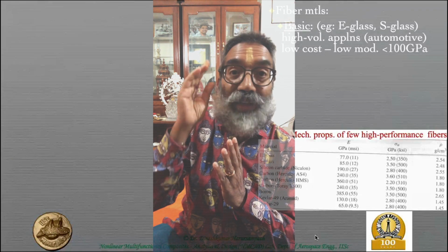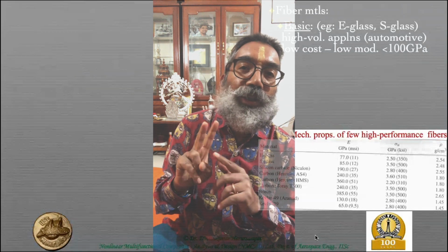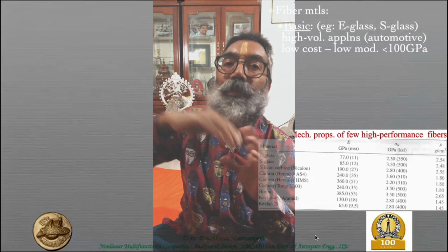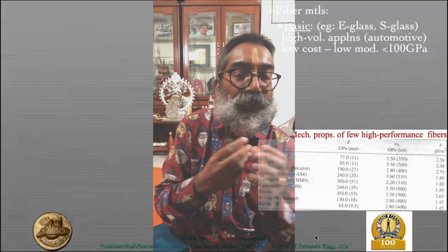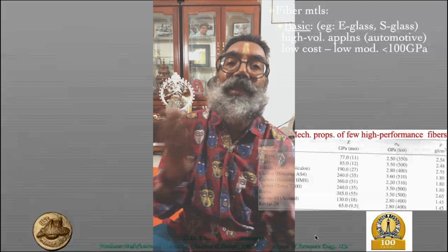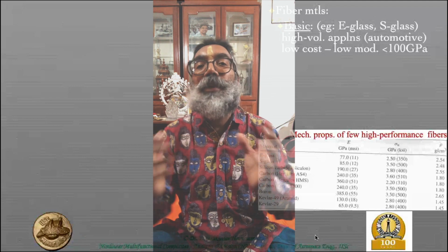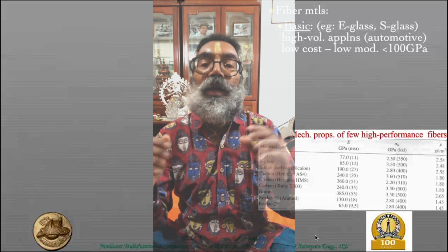But we are still willing to live with it because ductility is important from two perspectives. One is in terms of energy absorption, etc. The other, more important thing, is in terms of shaping a structure, making a particular component in many complicated shapes that are required for the flight vehicle structure. The airfoil shape, etc., even a T cross section or channel cross section with the appropriate chamfers, etc. But you know that these are available in the form of prepregs, which is a semi-wet kind of situation. So you can actually shape it into a particular thing in that wet state and then cure it.